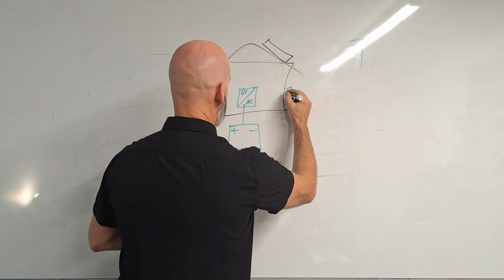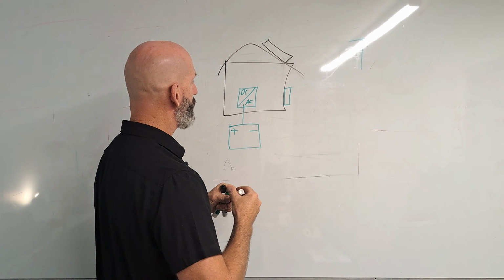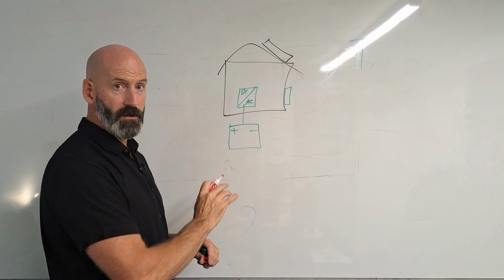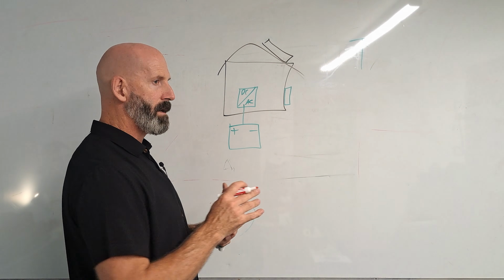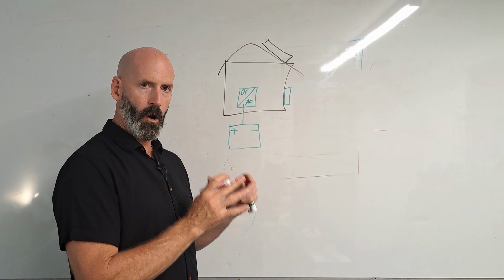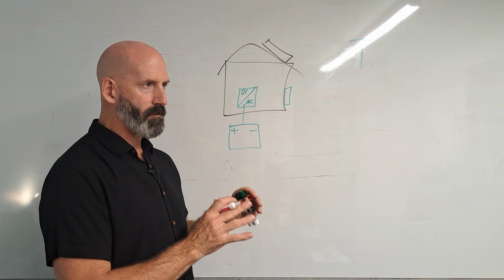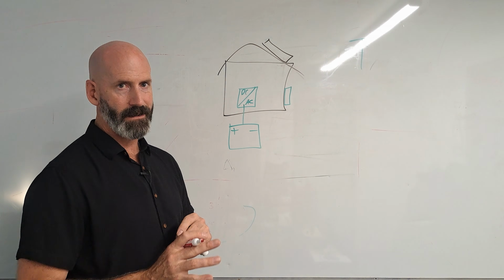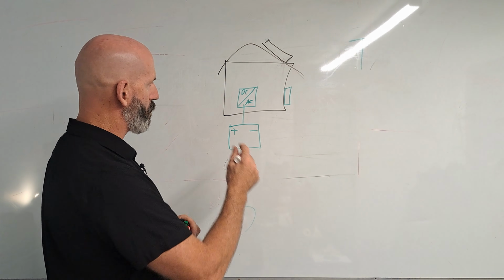We have our switchboard. Now, this system is designed to work with a completely different set of batteries. You'll find most hybrid batteries and most off-grid batteries are completely different. You'll find hybrid systems that use off-grid compatible batteries, but for systems that are primarily hybrid systems only, you can't augment them to an off-grid system and the batteries aren't compatible because they can't handle this big peak discharge that we're about to talk about.